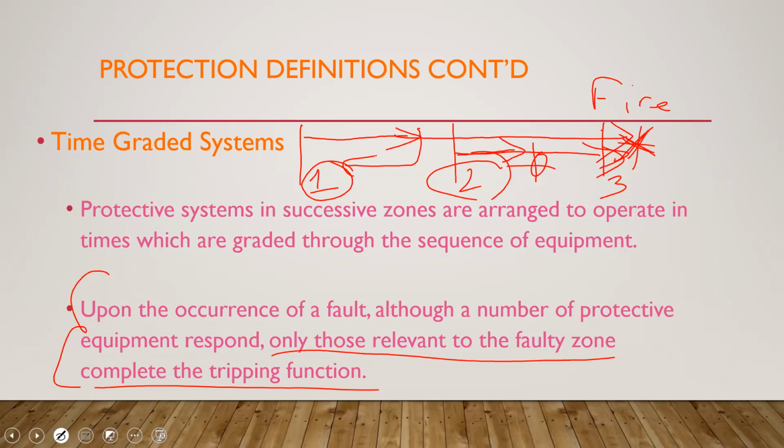Why? Because Hope would see a larger current because it is closer to UE. So its breaker would operate faster because the relay would be seeing a larger current. But remember, I just said everybody would see the fault. But at West King's House, whilst it sees the fault, it would be seeing a smaller fault current, so it would be operating slower.